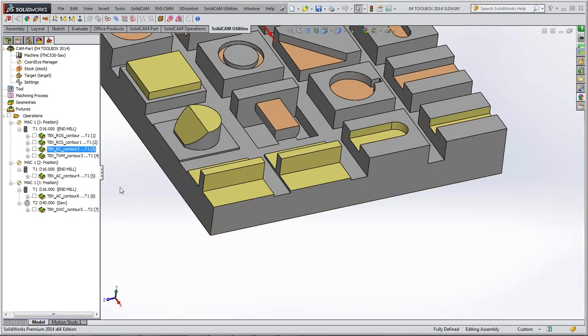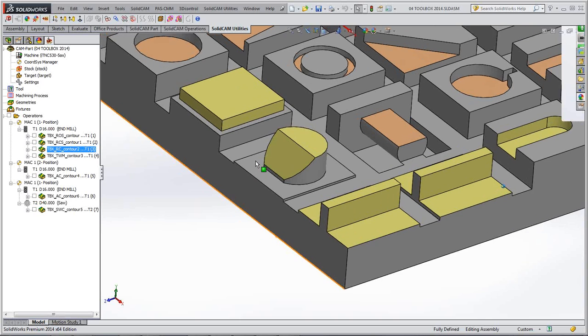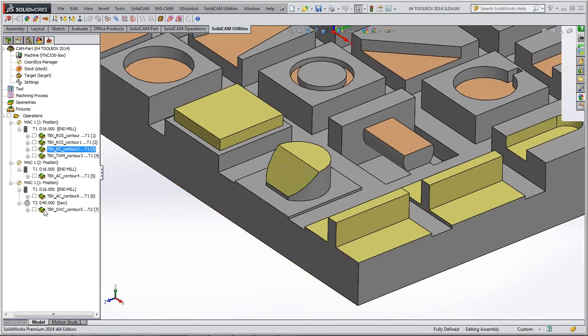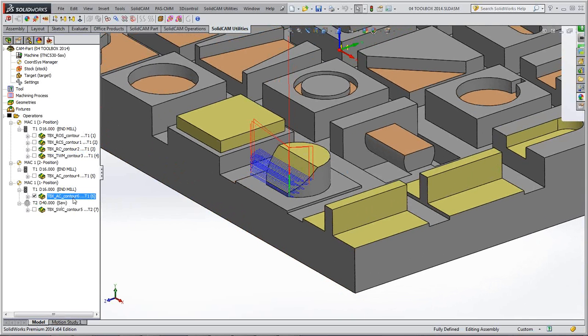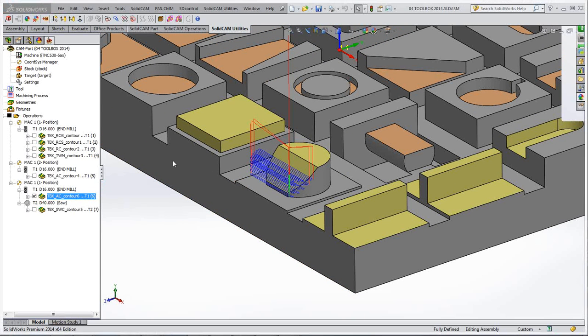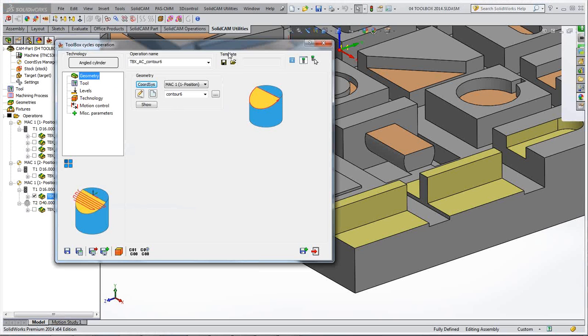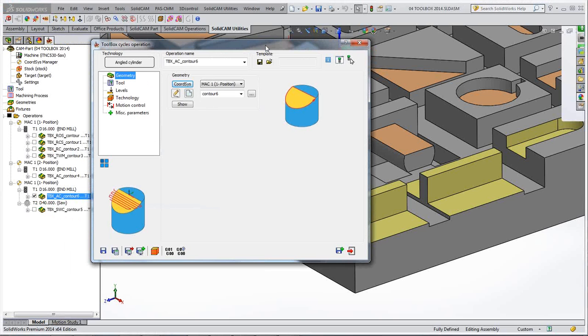And another one that I think is quite a handy thing is this little one here, this is our cylinder angle strategy. This might be a quick and easy thing to do with your machining in 2.5D. Remember, this is 2.5D we're talking about, so not a 3D operation. If you wanted to create an angle, you would have to put a draft angle or something on an existing contour. This just makes life easy if you need to cut across the end of something like this.